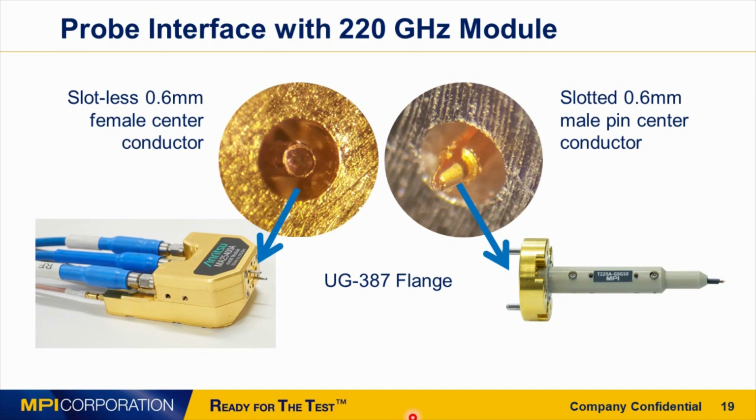The new broadband probe utilizes the unique 3D MEMS Titan probe tip technology that is well established for measurement applications up to 110 GHz. The tip shape of the 3D tip makes it easy to monitor the probe contact point under the microscope. Adjusting this probe to the DUT contact pads is very easy. That is why even inexperienced system operators can accurately reposition the probe on the DUT pads and thus achieve high repeatability of the measurement data.